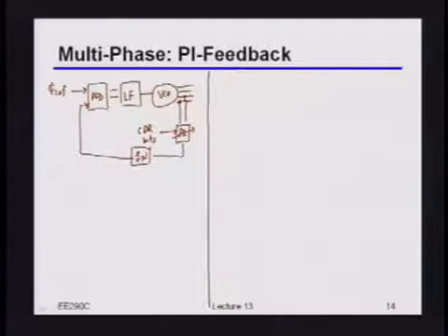So the idea here is actually very similar, right? Because now, instead of introducing that phase offset in the forward path of the loop, you're going to introduce the phase offset in the feedback path of the loop. And the advantage of doing that is that, by doing this offset in the feedback, I just have to offset one of the phases that I'm using for feedback, and all of the rest of them will naturally track. Now, it also has the caveat that these CDR updates experience the PLL feedback transfer function. But since you typically want a low CDR bandwidth anyways, that's not too big of a deal.